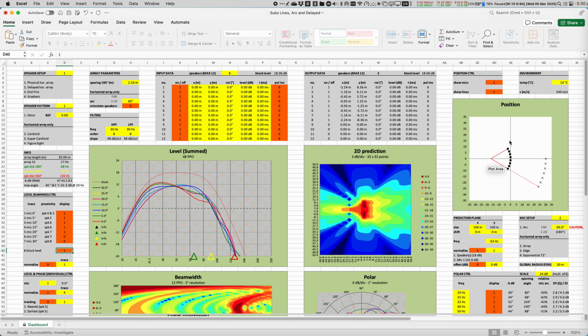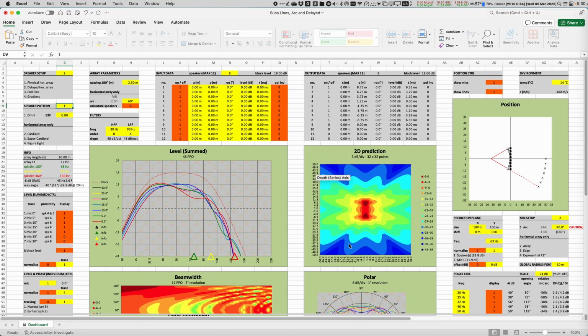Important thing is that in the focal point, all the speakers arrive at the same time, and because of that is where you will have the maximum summation. But when you do electronic delays, the rear will have the same directivity as in the front. So why? Because as we explained before, electronic delay is not moving the system, but is adding more latency.